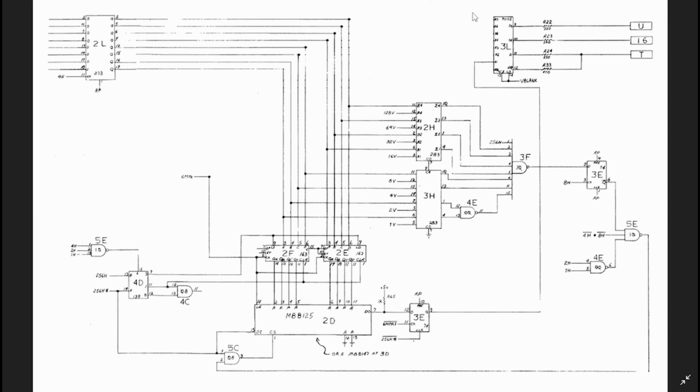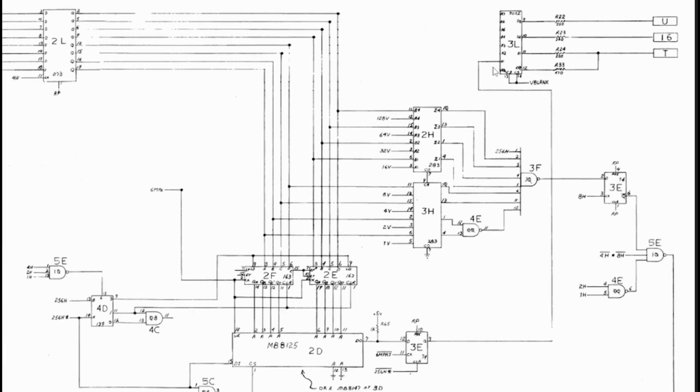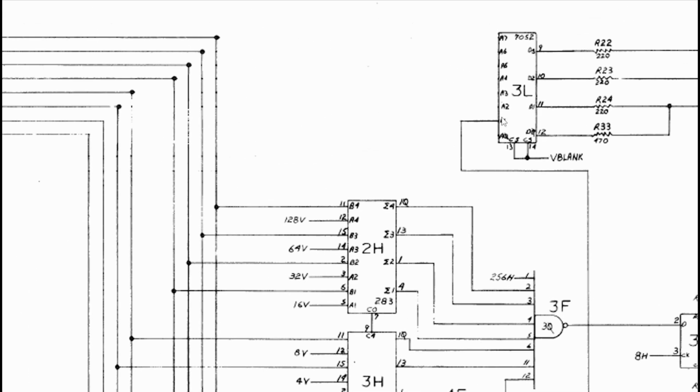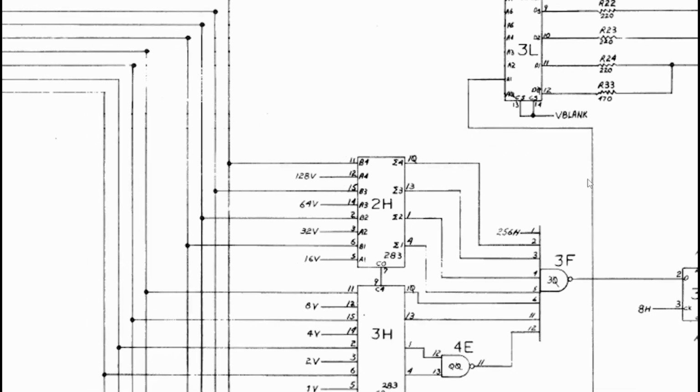And this bit here is just our color PROM, with our RGB outputs, and you'll remember that previously we were using A7 down to A2 for the tile map, and then when we had a pixel to be rendered we were using that A0. Now here we're using that A1. That's now the input to our bullet.